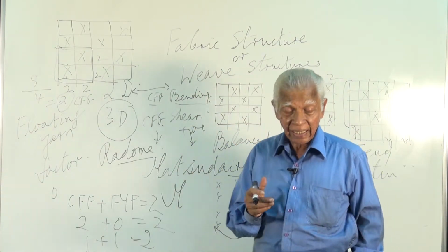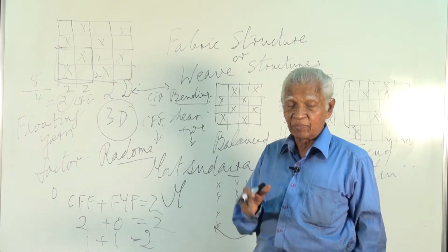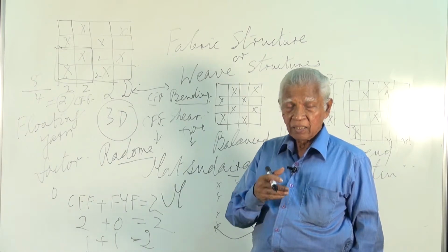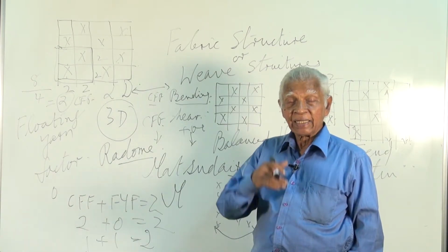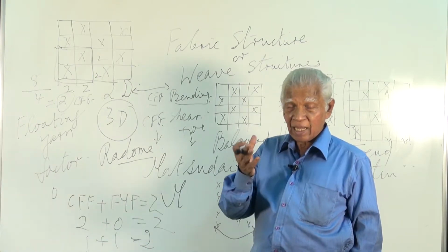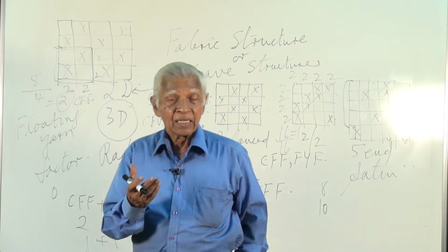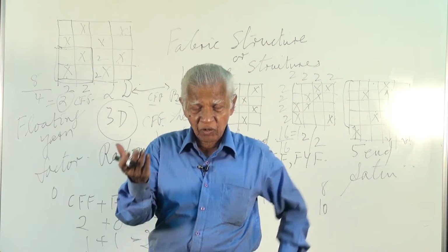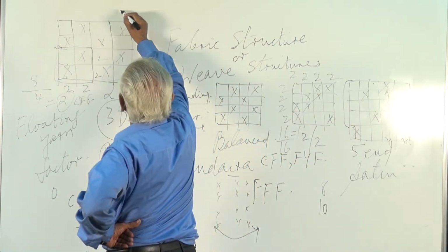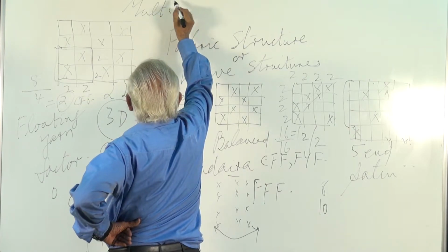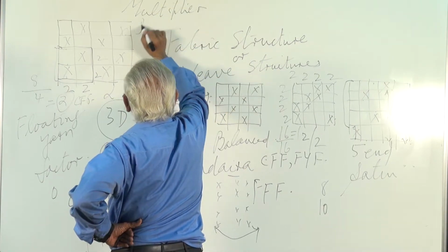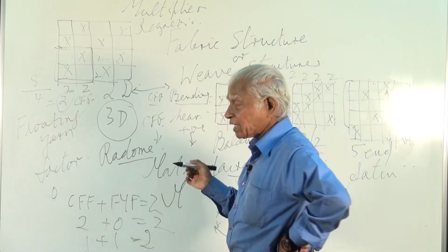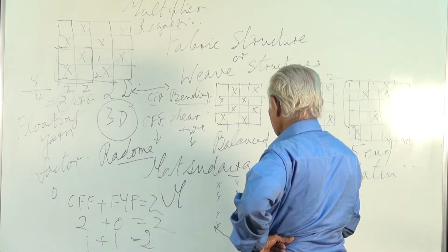So Matsudaira carried out a very extensive study on the effect of fabric structure on various properties such as the tensile properties, bending properties, shear properties, and total handle value, and he established various relationships between the various parameters and the mechanical properties, and also came out with prediction equations by multiple linear regression analysis. So using this formula, the mechanical properties of the fabrics can be calculated using the information on structure.